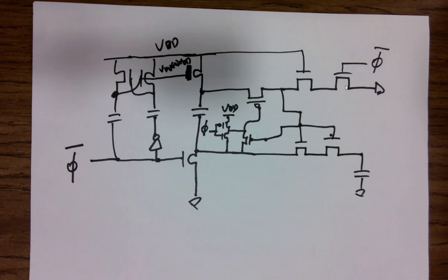This is all 0. Is this NMOS turning on or turning off if this is 0? Turning off. So which means it's not grounding this point. Okay, it's not grounding this point. So it's blocking this point from shorting to ground. And also, what about this one? The gate of this NMOS is shorted to VDD. So this guy is always on.